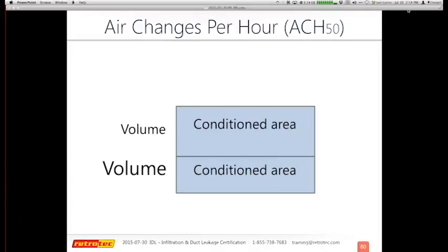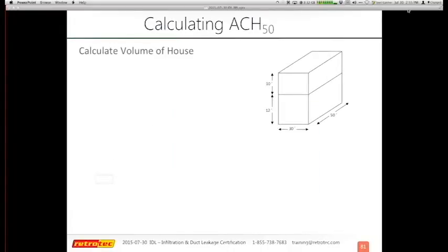I know that's one of the things that Southface preaches and tries to use. Other third-party verifications use that for blower door, and it's one way to show leakage. This actually is trying to also show ventilation or air movement throughout the structure. So I feel in the future you'll end up doing both, confirming if your house is tight, and also whether you have enough air moving through the house.